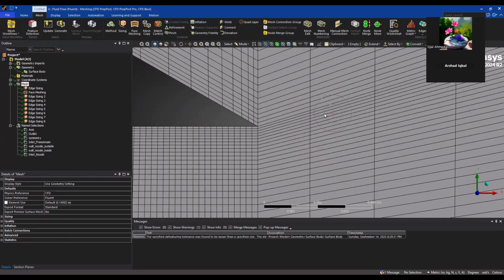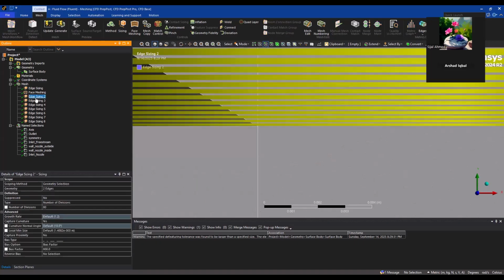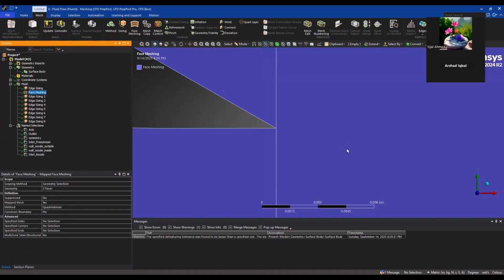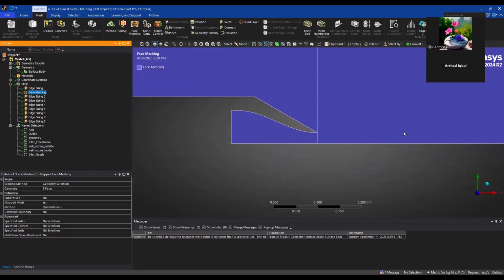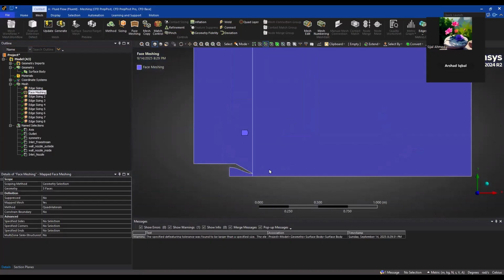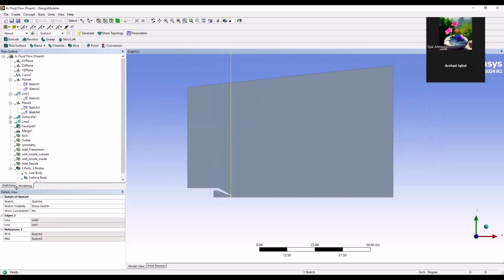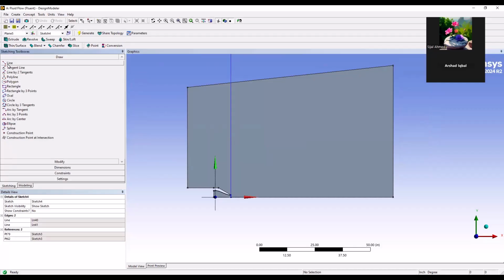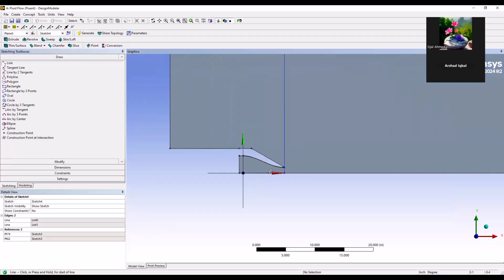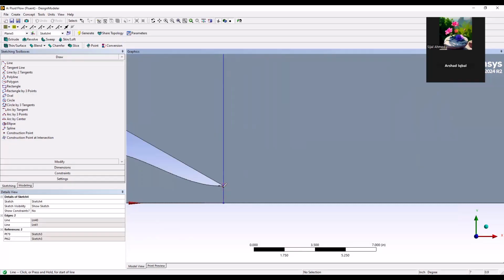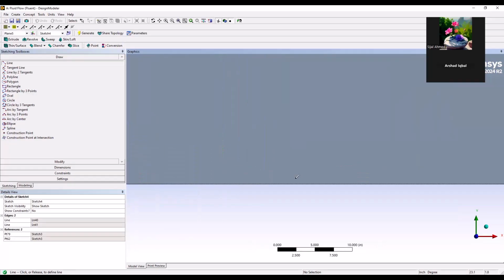Okay, now we should work on this biasing, which is here. Not here, but along the length. The problem is that we don't have the control here. So I need to make one more division in the geometry. So for that, I'm going to geometry, and I will go to sketch number 4, sorry. And I will make one line here. That will divide the geometry into multiple parts.